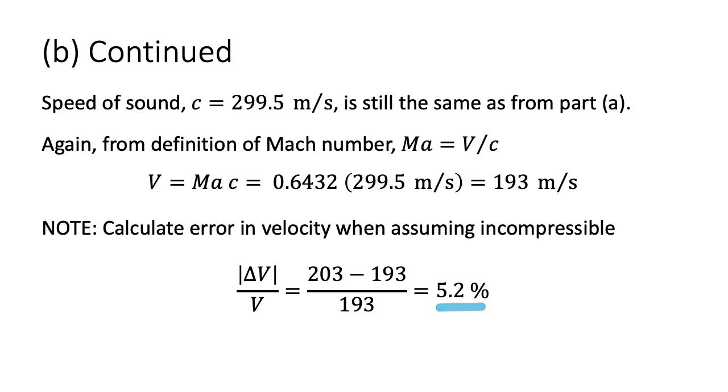Note that for typical engineering applications, a reasonable threshold for error below which we would reasonably neglect a term in an equation is about 1%. Thus, 5% error at a Mach number of about 0.64 is consistent with our threshold at a Mach number about 0.3 for including compressible effects.